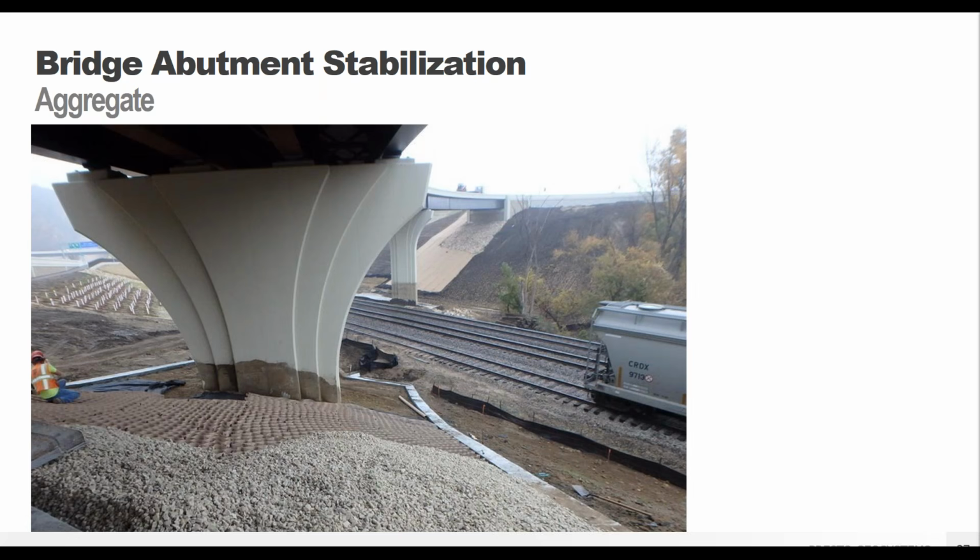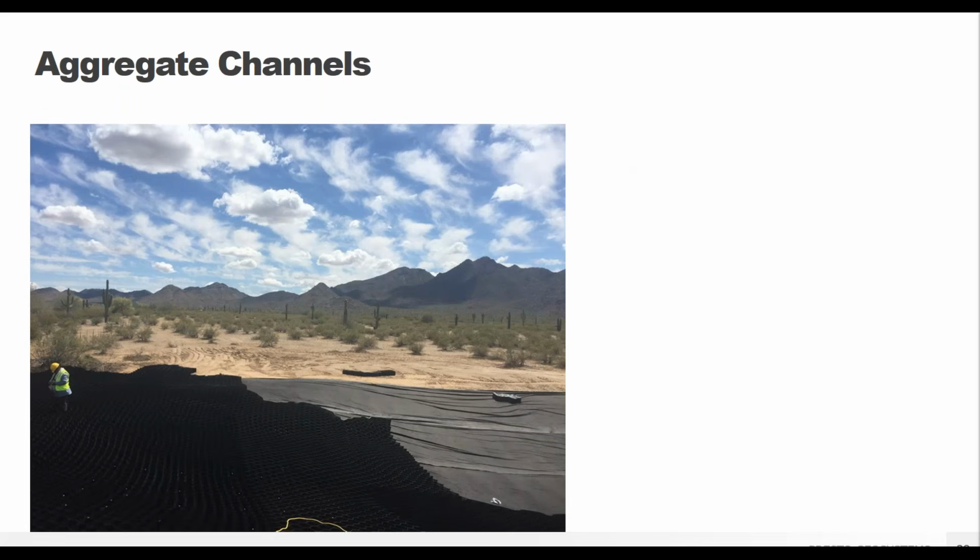You can also just handle a lot more complicated slopes than you would with just riprap stones. Riprap stones need pretty specific conditions to be able to hold themselves in place on large and steep slopes. And with the GEOWEB system, you just have a lot more flexibility for the slope angle, how well or not graded the slope face is, and then also going around the abutments.